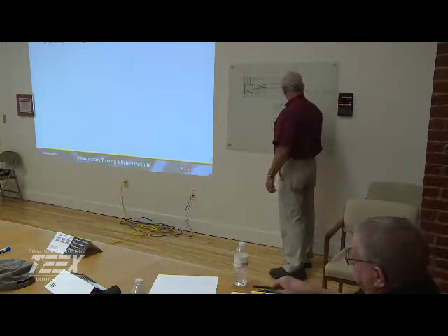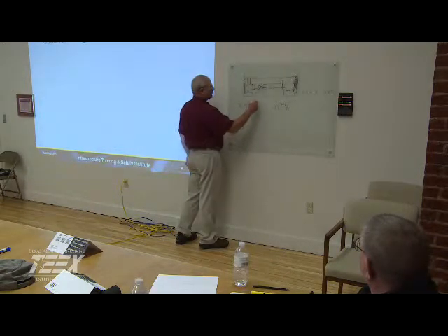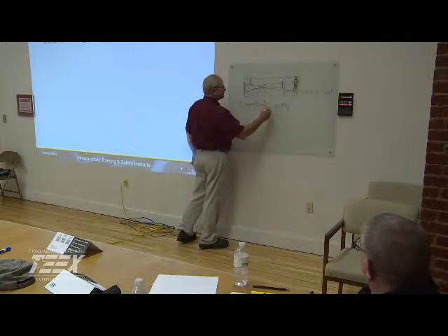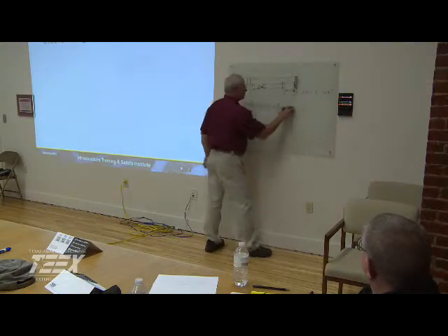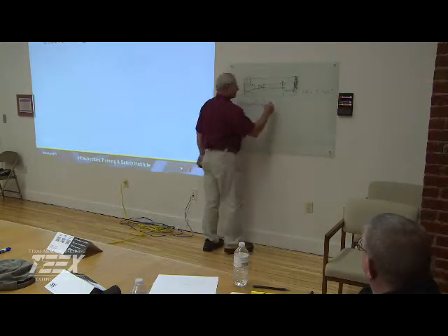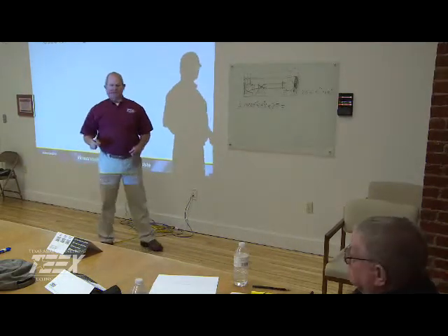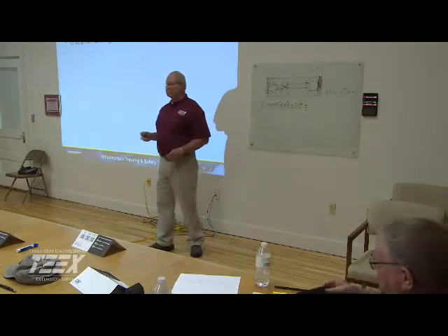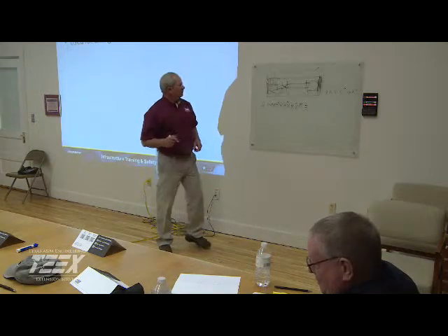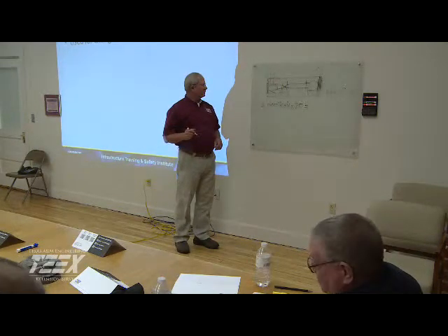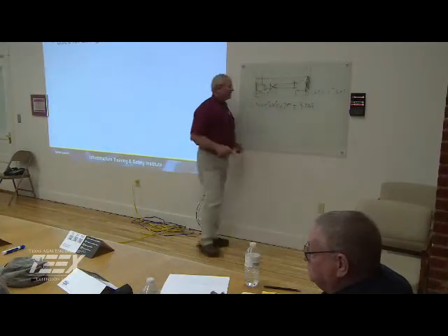So we have an 8-inch line, and let's say it's 75 psi. So if you take pi, 3.14, times 4 times 75, let me erase this off there. Okay. Times 75 pounds or psi. Somebody got a calculator? Multiply that out real quick. Anybody got a calculator sitting around? Oh, he's got one. The engineer has it. 3,768. That's a lot of force.